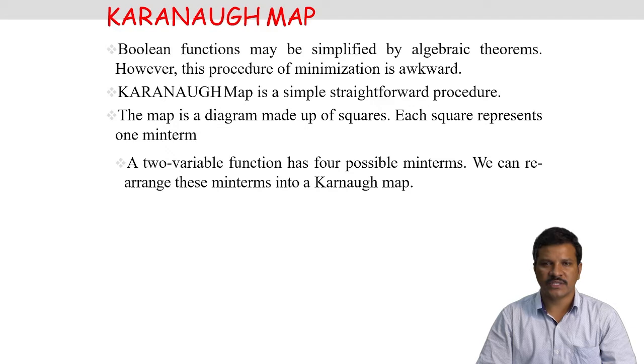The main purpose is that if we convert any Boolean function into NAND gates or NOR gates, then at the time of implementation we can easily pick up those NAND ICs and NOR ICs. All gates are replaced with a simple uniform gate like NAND and NOR, so that we can easily pick up the ICs and connect them to achieve a particular realization.